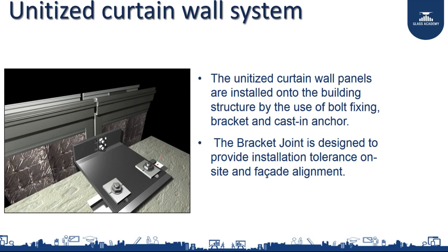This is your casting channel, this is your bracket. You do all your setting out, in and out, where you want the bracket face to be. So, you have serration here, which allows the locking of horizontal movement, and this bracket design itself will take care of all sorts of tolerances which are required at site to get a good system fix. And then what happens here, it transfers the dead load. So, the bracket design takes care of dead load first. Second, it takes care of restraint as well against the wind.